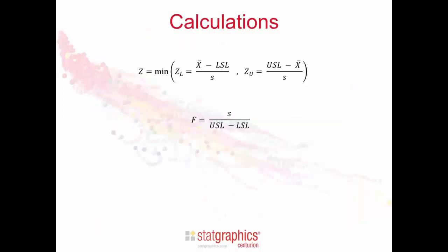Now, I've written down the criteria that are used for accepting lots in Military Standard 1916 when you're dealing with variables. It works very similarly to Z1.9 with respect to z-scores. I take a sample of items from my lot. I measure every item. I calculate the average. I calculate the standard deviation.